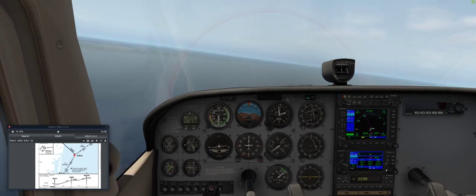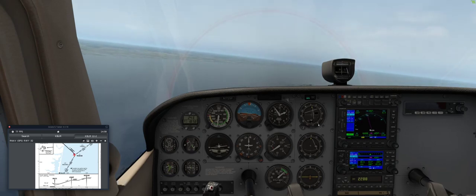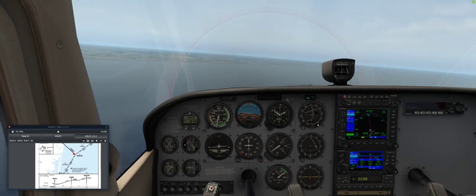To 1700, and you see that the glide slope as well as the localizer indicators on the CDI are now showing. That's the first thing I noticed earlier that should have clued me in that I didn't have the actual approach selected and programmed in.